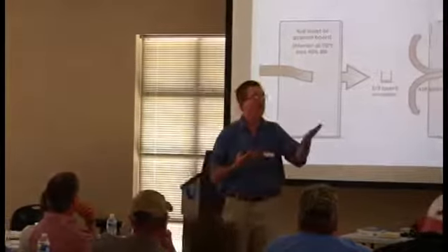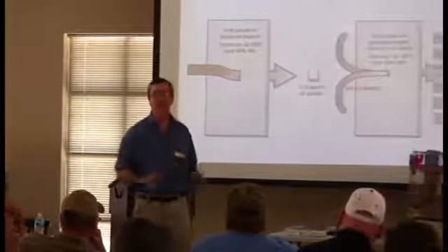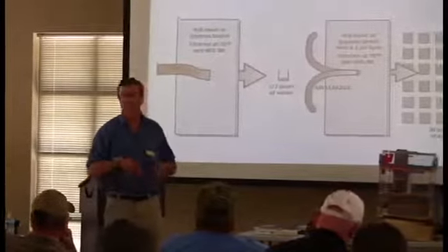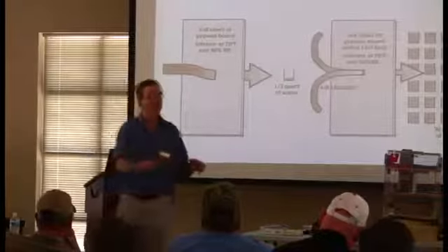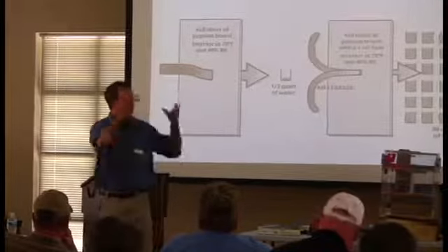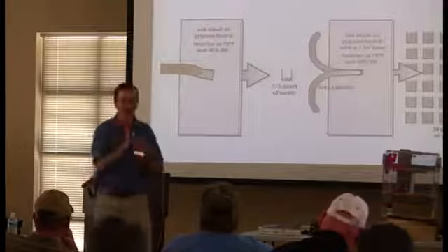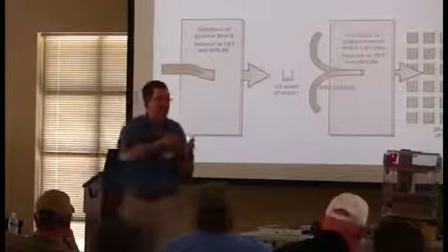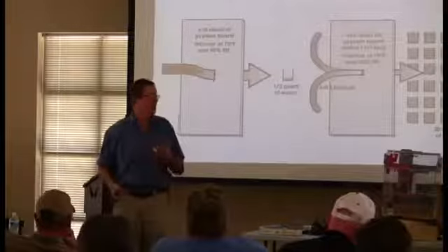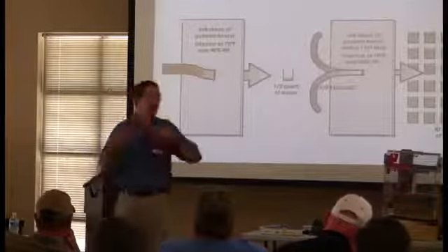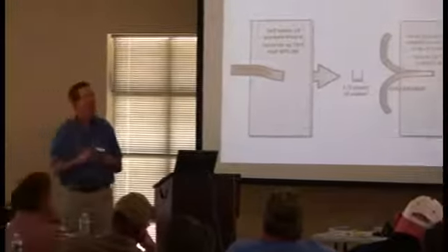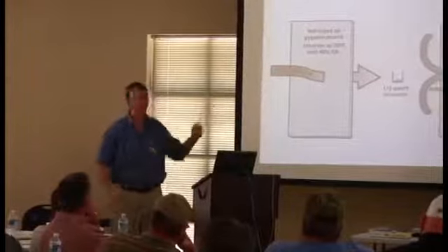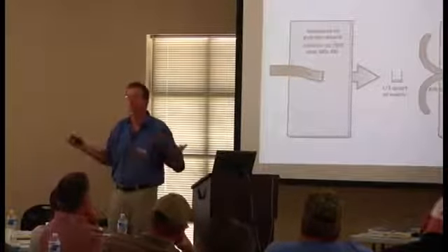Right. You can install unfaced fiberglass batts to your heart's content. You can install paper faced batts as well. Personally, I like the unfaced kind. I actually think they friction fit a little better, and people obsess with compressing the batt to staple it in. I actually think you're better off not doing that. That's my personal opinion, but you do not have to have a vapor retarder. You do have to have an air barrier, because the air barrier is what keeps the moisture from flowing. Does that work for you?